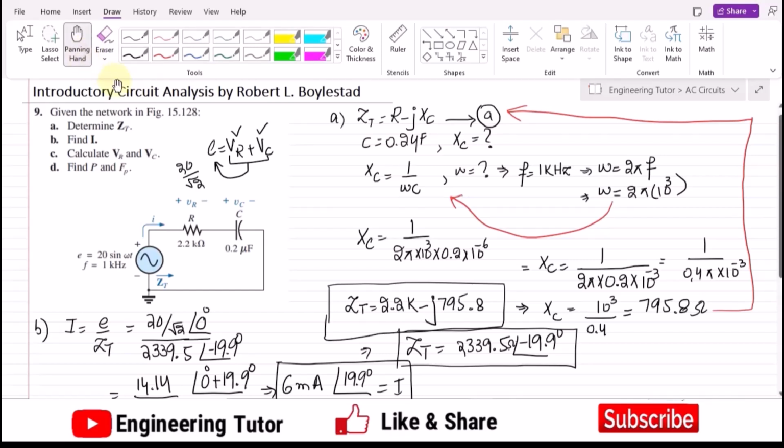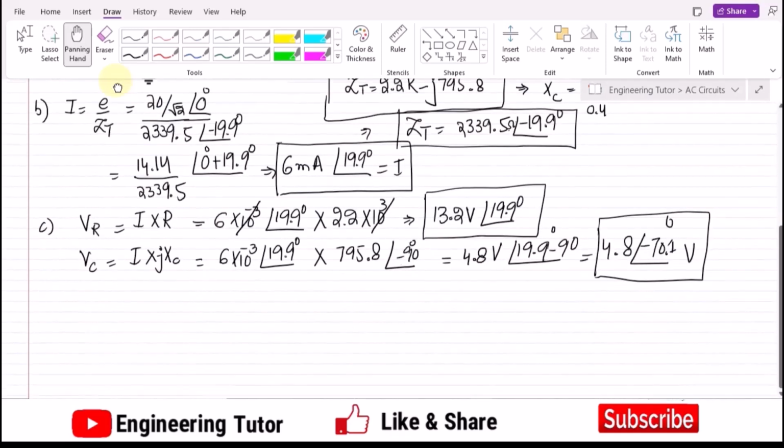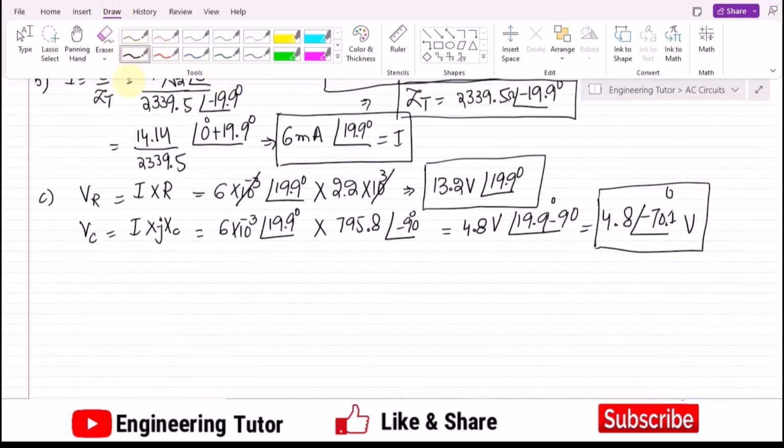So in part D of our question, what I have to do is find the power and the PF, which is the power factor. So let me first find the power factor, because that is the important one. Power factor, as I have previously told you, is R divided by ZT, which is also equal to cos of theta, where theta is the angle between the total voltage and the current as well.